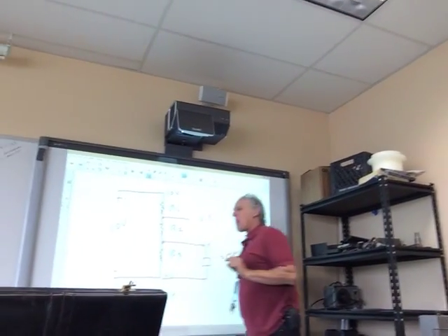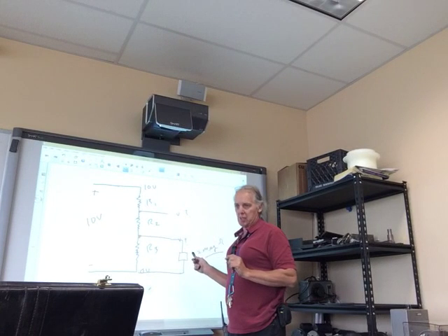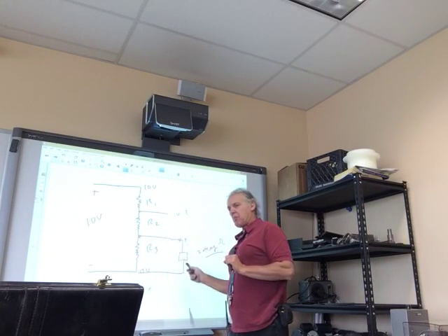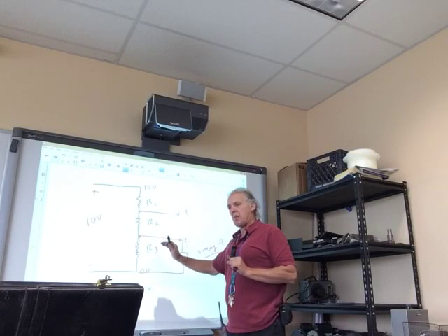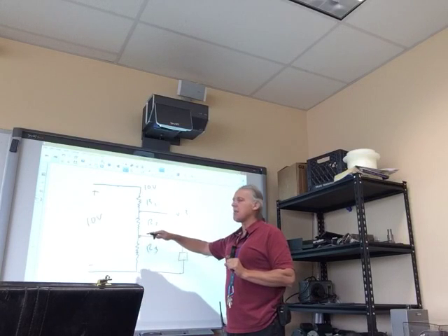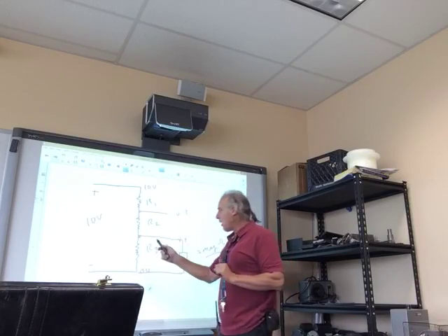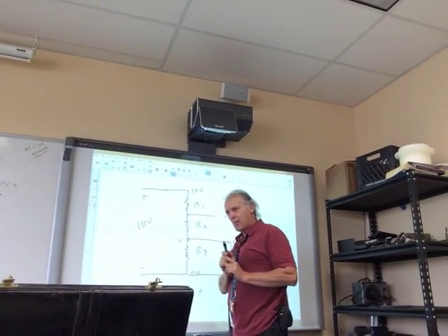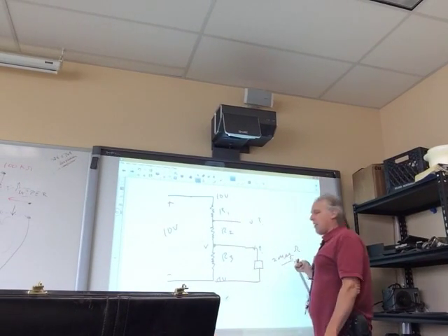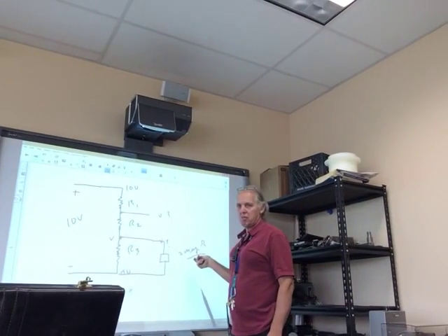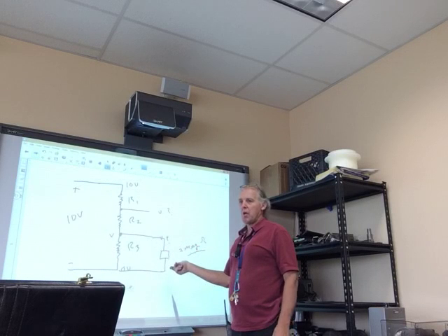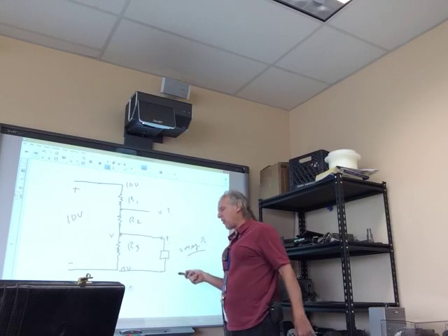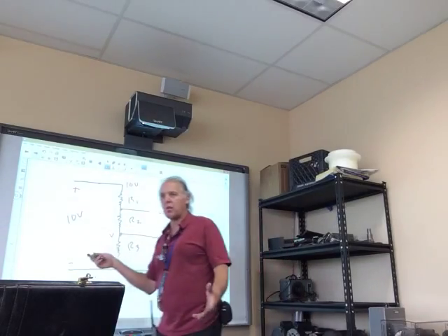That presents a problem for a lot of circuits because they're current-driven. If they're current-driven, voltage dividers have a problem. What is it? They change. We want this voltage right here to stay the same if we can. So this works really well for large resistances. If I put a motor on here, I got a problem. One thing, a motor's variable anyway, but even that's a heavy load, okay?